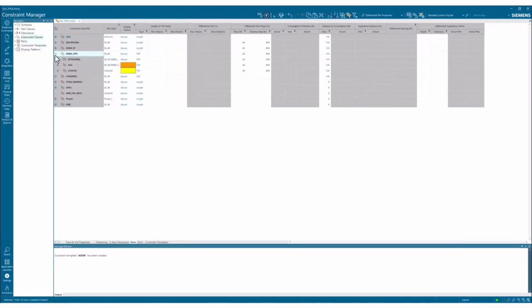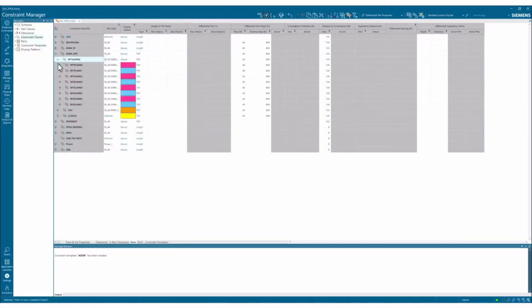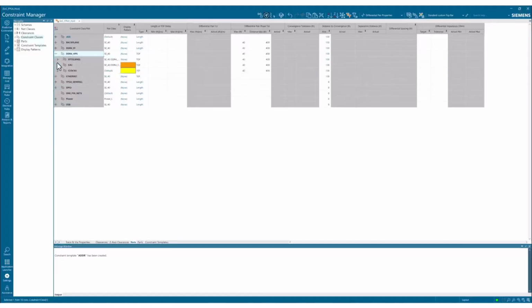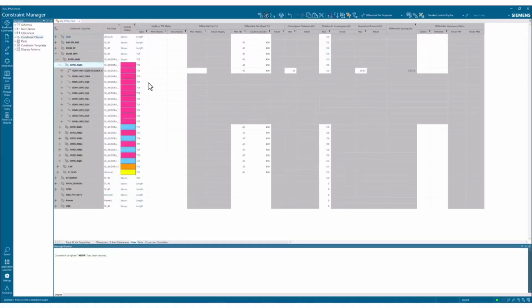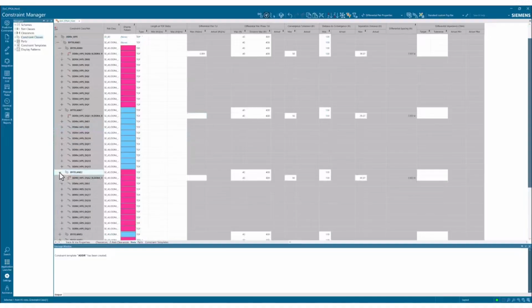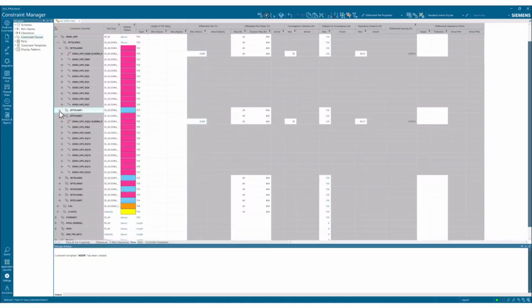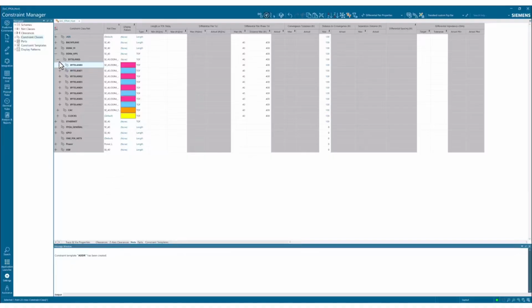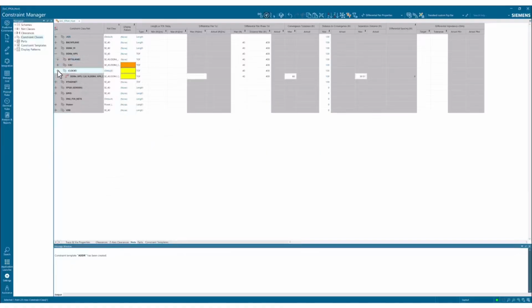We'll start by setting up these differential pair tolerances, and that is under the differential pair properties view. At least the easiest way to see it, we can navigate to the strobe signal. Okay, we add a 1 picosecond tolerance to strobe 0, and it automatically gets rewritten in terms of nanoseconds because that's the default unit for this design. And now I can copy, paste that, or in this case just drag that cell down to apply to the other strobes. The max differential pair tolerance column is only available for those differential pairs, so I don't need to worry about accidentally applying this to other signals.